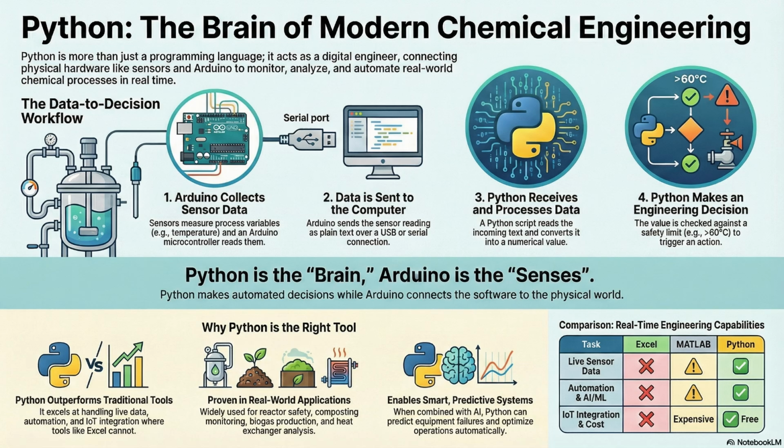So all this physical information gets turned into a tiny voltage signal by these sensors, but that signal is still analog. Python lives in the digital world. That's where Arduino comes in, right? As the go-between. Exactly. The Arduino is the dedicated data collection unit. It's the reliable middleman. It does two things really, really well. First, it reads that analog sensor signal and digitizes it. It turns it into a number, and it does this very, very fast. Second, it sends that digital data, usually over a USB cable, to the main computer.